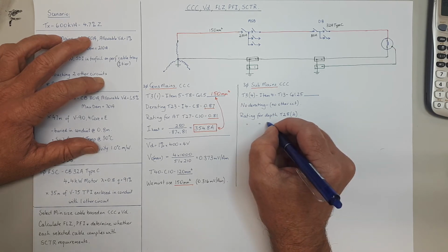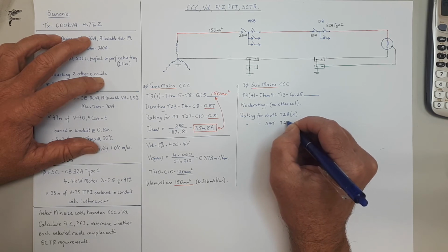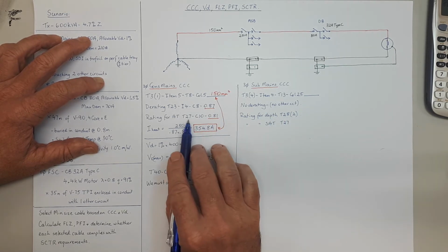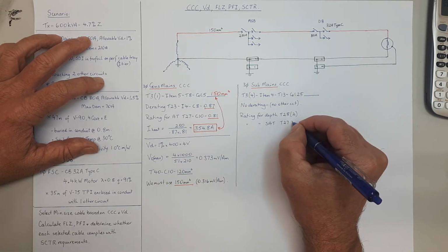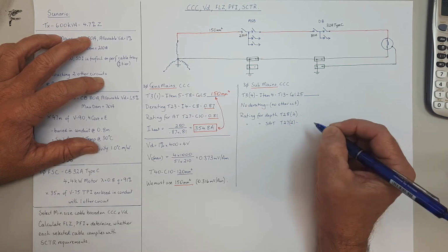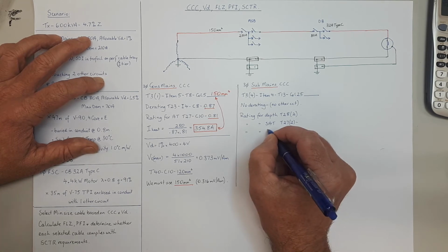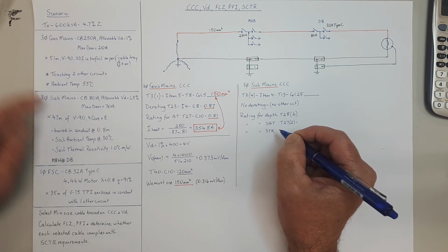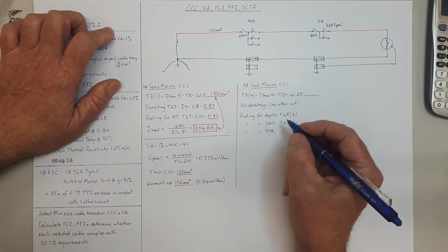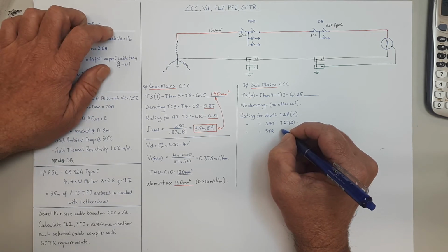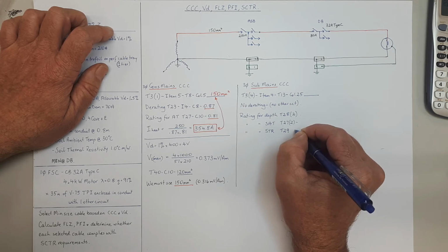And we've also got soil ambient temperature. Ambient temperature is table 27, but because we used table 27.1 there, this is table 27.2. And there's a rating for soil thermal resistivity. I'll just call it STR. And our soil thermal resistivity there is 1 degree C meters per watt. Alright, so that's going to be table 29. So there's a few ratings there we have to contend with.